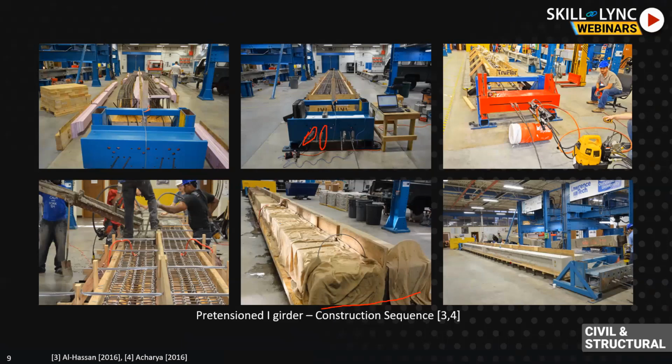So what will happen is that when you look at a picture, if your strands are on the bottom, the force will be somewhere here, right? On the bottom, on both sides. If the force is on the bottom on both sides, obviously this beam will try to bend like this, right? So there is an initial deformation here immediately after release. We call it camber, initial camber.